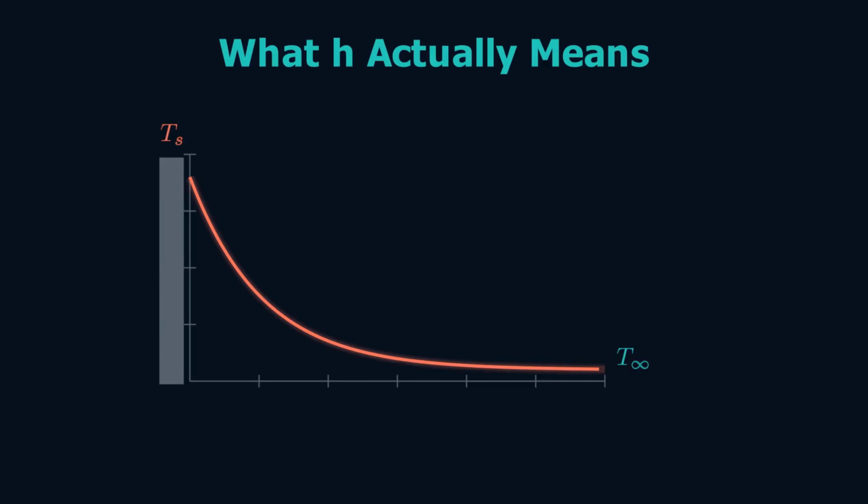Before the recipe, one picture that makes everything click: the boundary layer. Right at the wall the fluid is stuck, it cannot slip, so its speed is 0. That motionless film can only pass heat by conduction, just like a solid. A little further out the fluid is moving in, sweeping heat away. The temperature bends across this thin layer. All of convection lives in that bend.